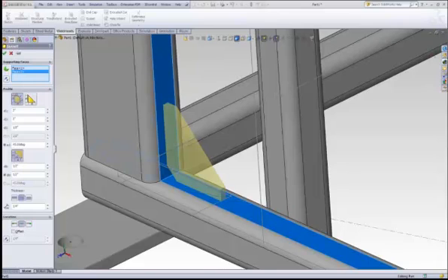Oh, I got a question for the previous feature that I just put in, that foot. Do the properties carry through with the sketch to the cut list? That is a good question. My answer to that is yes and no. I may need to get back to you on this, because I have done it before, but I can't do it with that 2D sketch. I did try it in this case, and it did not work. So I'll have to get back to you on the answer to that question. I believe if you drag and drop in a derived component, the properties come over, but not necessarily a 2D sketch, which I did here.